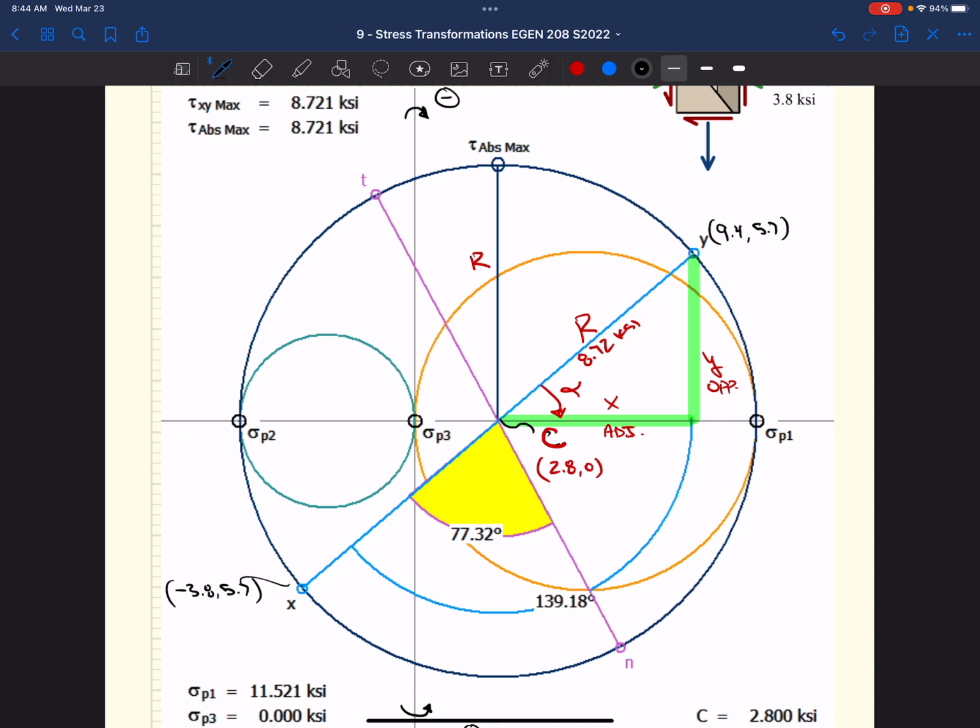But when you put a shear stress on it, it finds the plane that has a big tension stress in it, and that plane depends on the initial stress state. If we put it in pure torsion, we're going to have these two dots on our y-axis. Our principal stresses are going to be 45 degrees to that, and you're going to get this 45-degree spiral, which is really cool. Google it too.